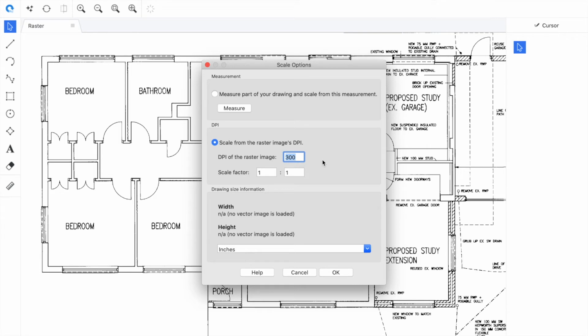So in this case, we can see that it was 300 DPI. We usually advise that a sweet spot, if you're setting the DPI when scanning the drawing, it should be around 200 to 500 DPI. In theory, if you have a really high DPI, then it will increase the accuracy, but you should only go for that if you've got a very simple image and you're worried about like nano millimeter sort of measurements. So we see the scaling is fine here.